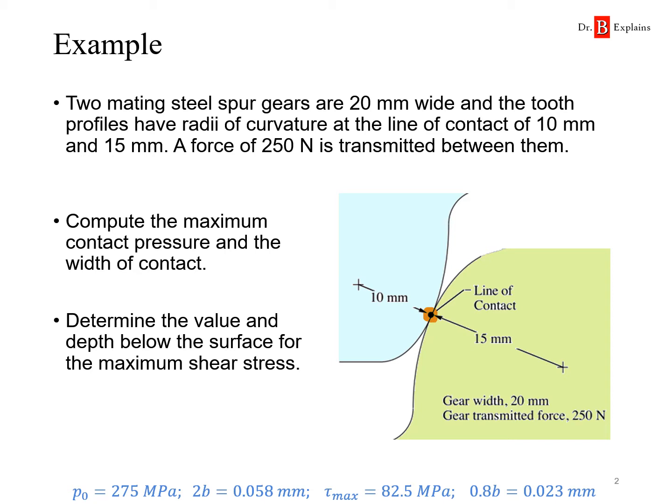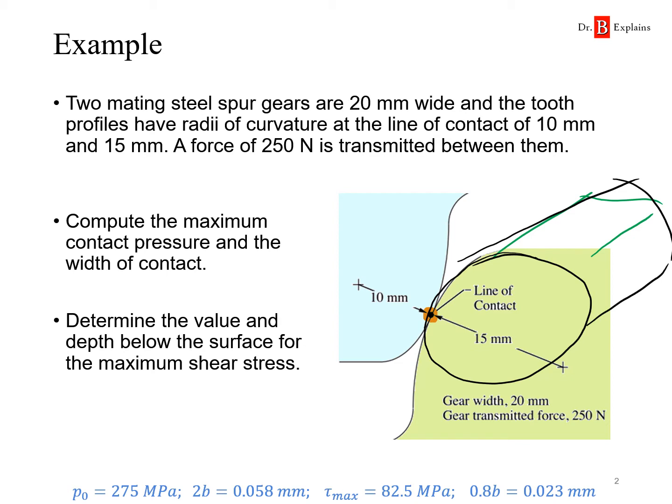Essentially what we're doing is treating the tooth of the gear, because remember these are in three dimensions like so, as cylinders, like if there was one cylinder like this in contact with this other gear tooth, this other part is treated as another cylinder. Hopefully that made some sense when I explained that video. Anyways, contact stresses, there's an easy way and there's a little bit more involved way. I'm only going to cover the easy way, which is through this example, again, on a separate video.